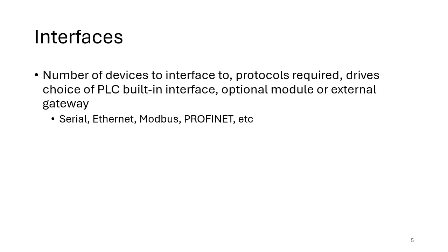For interfaces, you'd look at the number and type of devices you need to interface to. You'd need to look at the protocols required, and that would drive the choice of using either built-in interfaces, or maybe you need optional modules in the PLC, or you might even need external gateways depending on what's available from the PLC vendor and what's most economic for that particular application.